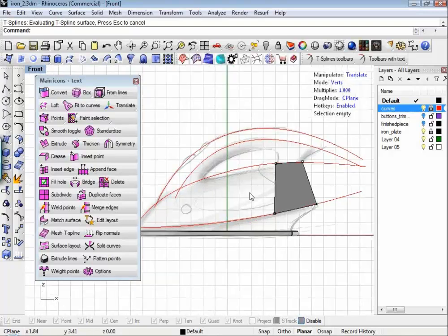By default, we're starting in smooth mode. I actually want to work in box mode, so with the heads-up display on, which I get by hitting Control and the space bar, which turns that on and off, I'm going to just hit the Tab key, and that's going to switch me into box mode so that I can build this out of squares.